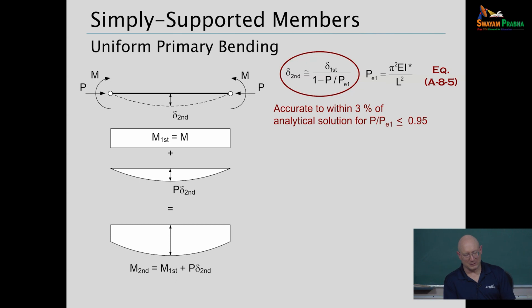And the result of this, you can get this from a geometric nonlinear analysis if you're discussing it from a finite element perspective, or you can say you're doing a second-order analysis, which means equilibrium in the deformed geometry, right? You're evaluating equilibrium in the deformed geometry.